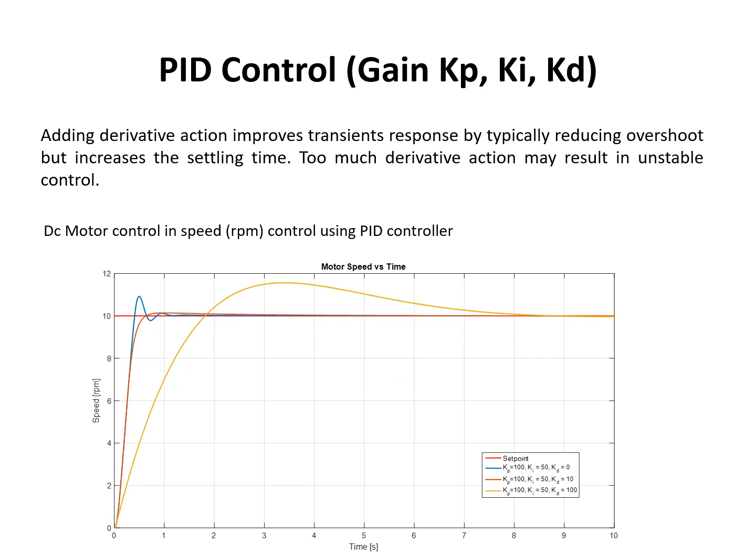So here we basically now have a full PID controller. In essence, the best solution we could find for our PI controller is the blue curve over here, which shows a very quick response but some overshoot and a steady state error of 0. Now we add the derivative term and we get this orange curve, where the response time is still very quick, almost exactly the same. However, the overshoot is significantly reduced and we get a much better response of our system.